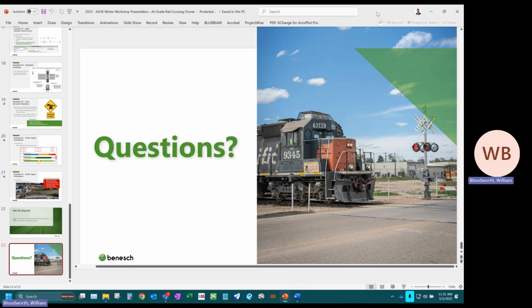I think those yellow curve signs we've actually done in District 7. They're on Peachtree Road, I believe. They're pretty effective, and high friction surface treatment the same. It's not just curves in urban settings, off ramps as well, even T ramps at signals. People tend to be coming off the interstate at high speed. So any place where there's a large speed differential, it's kind of the same countermeasures, different prediction model you would need to prioritize though.